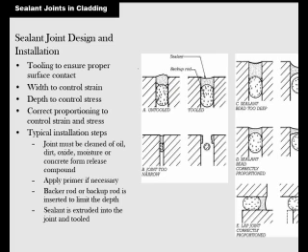So this is what it looks like untooled. This is a section cut through it, and this one's tooled. They've obviously run their tool down and made sure it evens out. This one, the joint is too narrow. Joint too narrow. That one looks like it's too wide, or maybe it expanded and then it pulled apart.